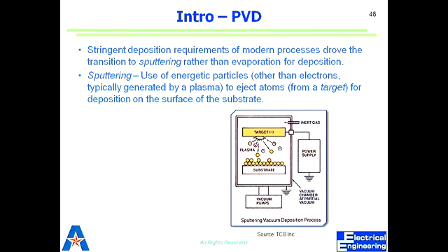So sputtering is a similar process. The only difference is now I call my source a target, because I'm targeting that sort of disk to dislodge material that I want to deposit. Right? So I'm targeting it with a beam instead of melting it. I'm targeting to dislodge the atoms in solid form, and then I want them to travel to my substrate.